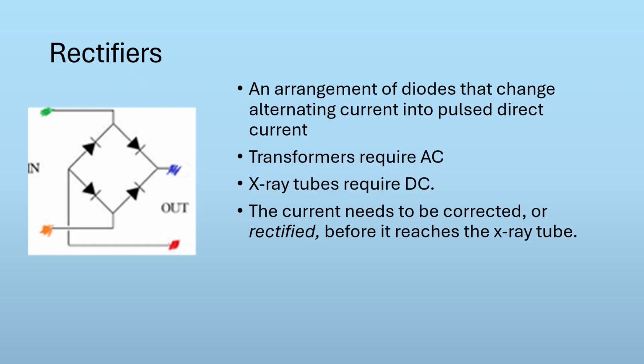And that's where we would like to connect to the cathode. But what about orange? Because it's AC, half the time the electrons are going to be coming from the orange. So bring the electrons in from orange, and again, they can only go to the left, and they have to exit at red. And so no matter which way I push electrons into the ring, they have to exit at red.